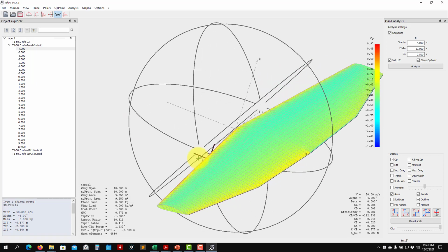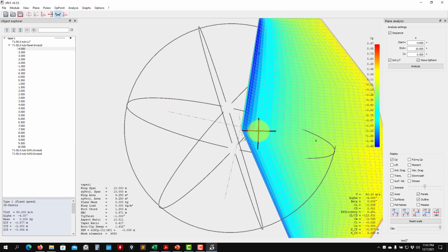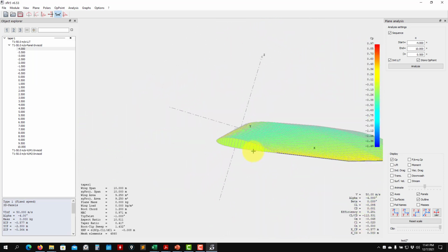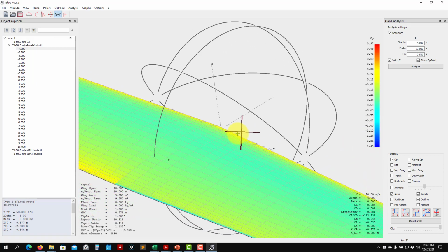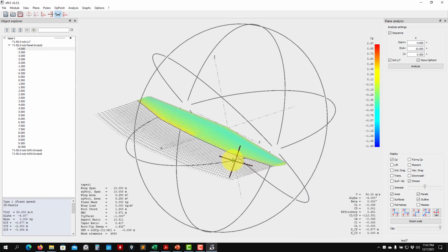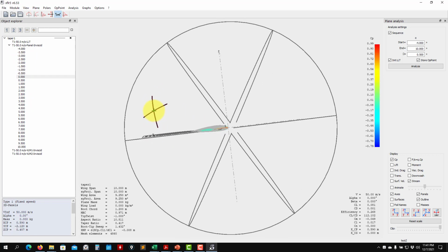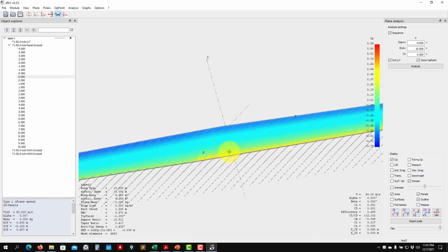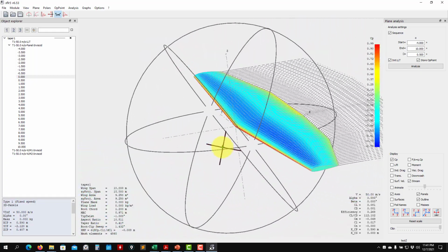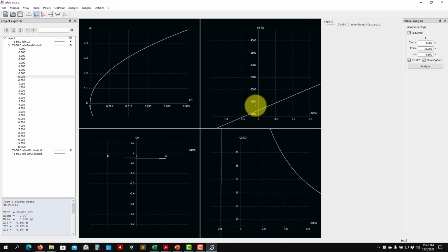Okay, so it is done. We have results. See that now we resolve the actual thickness and everything. It's not like in the vortex lattice, where it is only the camber line. We're resolving everything. Again, you can put your streamlines there if you like those colors. Let me save also. Put in 0. And you have there. So this is giving problems now. It's not resolving now the wing vortex. And let's look here.